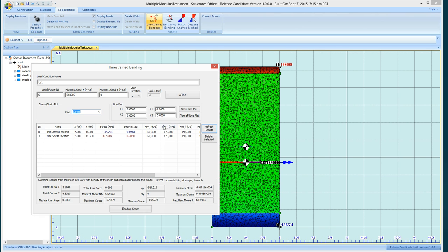Then for the material of these points, it gives the yield allowables and the ultimate allowables, and you'll see that we've got a tensile allowable of 150, and we're greater than that, and that's why that warning was thrown. It shows you materials that those points lie within, and then a multiplying factor for Young's modulus of the steel versus the wood. So the Young's modulus is 16.7 times that of the wood.